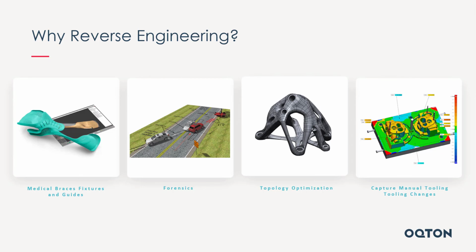Medical, medical braces and fixtures. That's why I use that hand. We do a lot of this with Freeform. That is reverse engineering as well. That's an example on screen of a design that we made to create a brace for somebody's anatomy. And that's an example where we did not use NURB surfaces or CAD. We actually designed right off the anatomy using the voxels. Voxels can be extracted straight from meshes and point clouds, and you can create designs and do CAD modeling on scans.